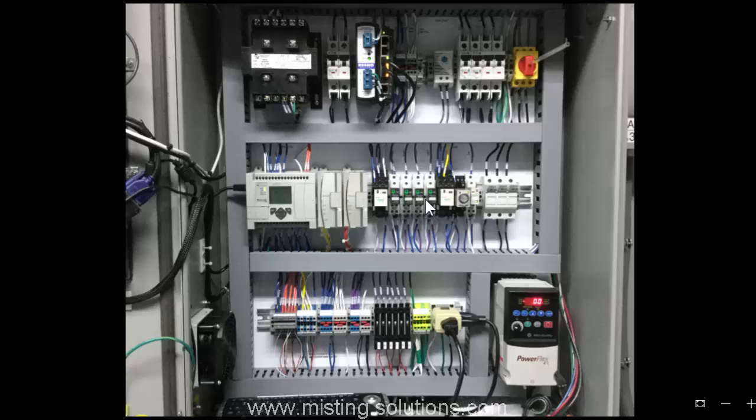There's also a signal, 24 volts DC, that gives an enable signal to the VFD, and then there's another signal when the system actually runs. It provides a 24-volt DC power out of this controller and energizes this run relay right here. This is a relay that actually does a variety of things when the system starts up.